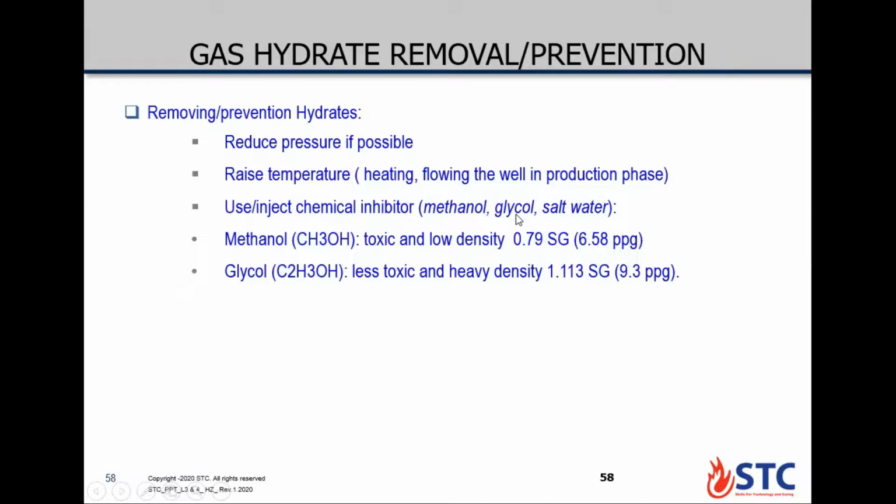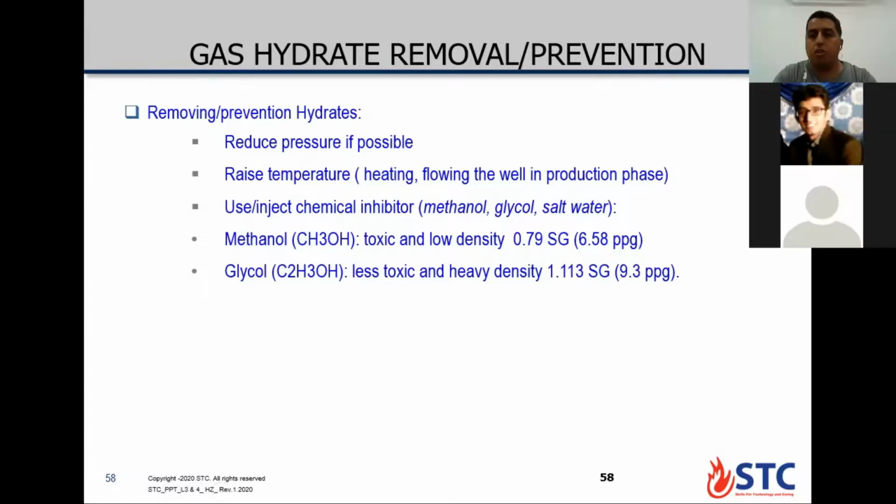Chemicals come in drums, so you can connect a small pump with a control line upstream, on the return from the well, and with a pneumatic pump, start to pump a small amount of methanol and glycol upstream of the choke, into the fluid coming from the well. This prevents the formation of gas hydrate. Methanol is CH3OH, glycol is C2H6O2. I usually prefer to use glycol because glycol is less toxic while using it during the killing operation.